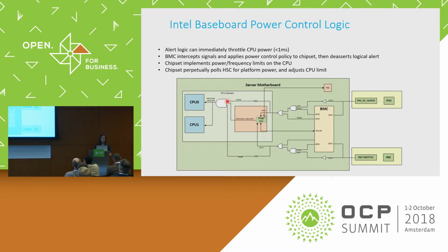When we run without that instant drop, if you put a power policy on the ME, or you try to implement some RAPL-based power control at the CPUs, you see the power come down gradually, and that slope, that time window, can vary. So you can either have an instantaneous power drop depending on the severity of the event, or you can have a gradual power decay down to your power limit.